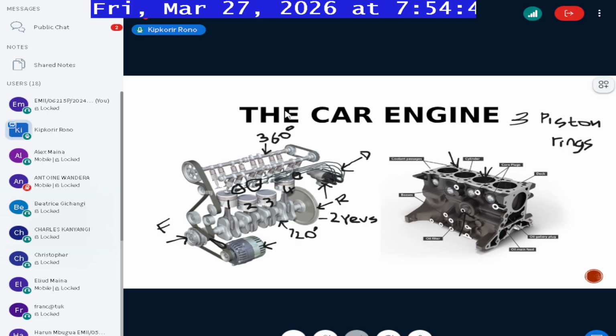Now, you also normally change the oil after some time. The oil change could be carried out from a scheduled maintenance program. But a scheduled maintenance program is not a very good way of determining when to change the oil in your car, because oil has two main, very critical functions. One is that it lubricates the moving parts in the engine. Remember, all the parts in the engine usually operate at a very high speed, so that requires a constant supply of oil. For example, the crankshaft and camshafts move at a very high speed.